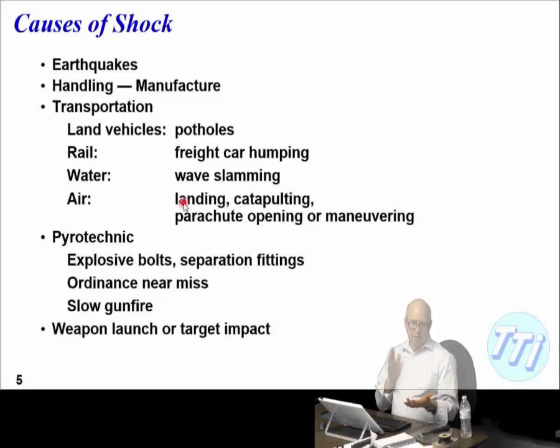Because the spine of the ones for the aircraft carriers are significantly strengthened. Because A, they need to be pulled apart by the catapult launcher, and B, they're then going to crash land. Literally, it's almost like a crash landing, and the tailhook can suddenly be jerked to a stop. And if you were to take an Army variant and try and land it on the aircraft carrier, it would just tear it apart. Just one-shot landing, you're done. But catapulting is very severe.